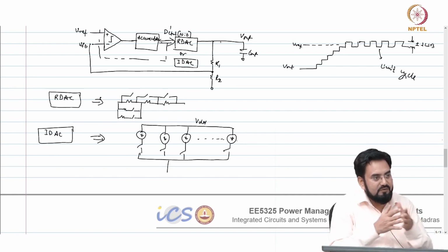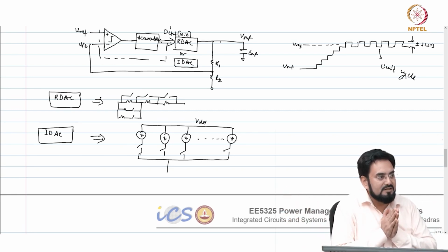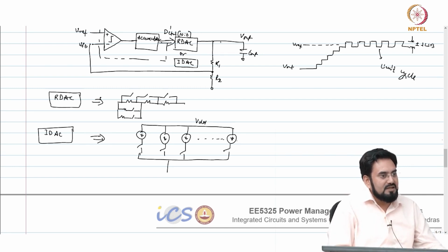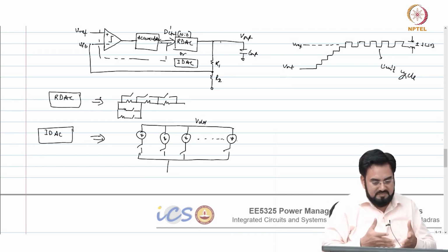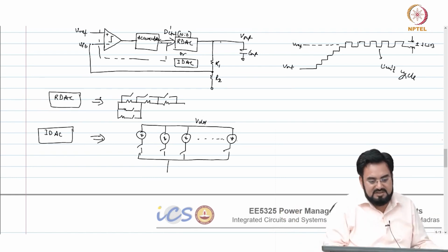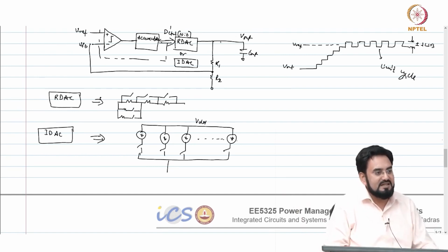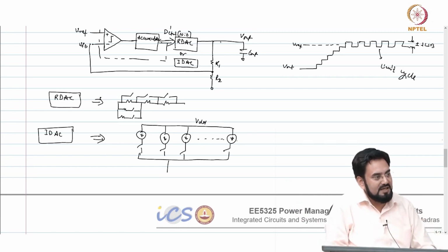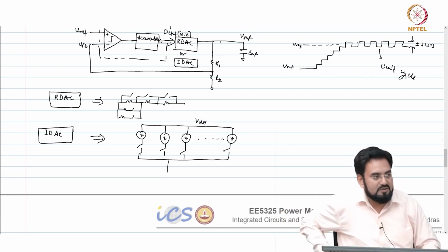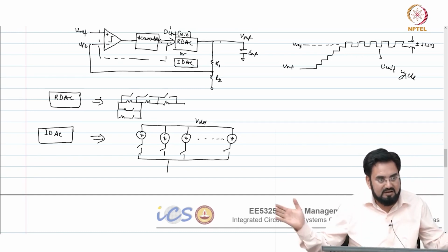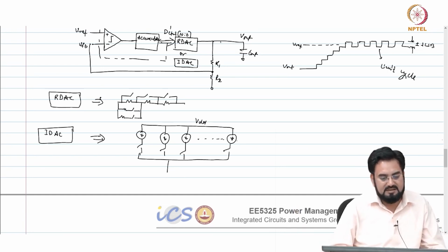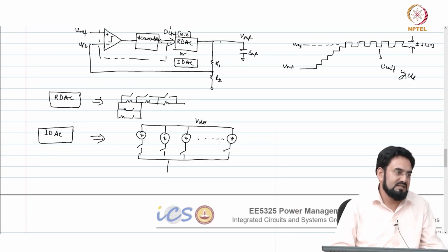okay, which means when all the currents are on, you will be supplying 10 microamp current. Now, you have to supply a 10 milliamp current. So, how many? You require 10,000 of these roughly. So, which means the resolution requirement here might be very high, not just 7 bit, but you may require 12 bit, 13 bit kind of to cover the entire range of the load. Okay, but if your load is fixed, then it is not a problem, but if your load is varying a lot, then the requirement for resolution would be very high in that case.